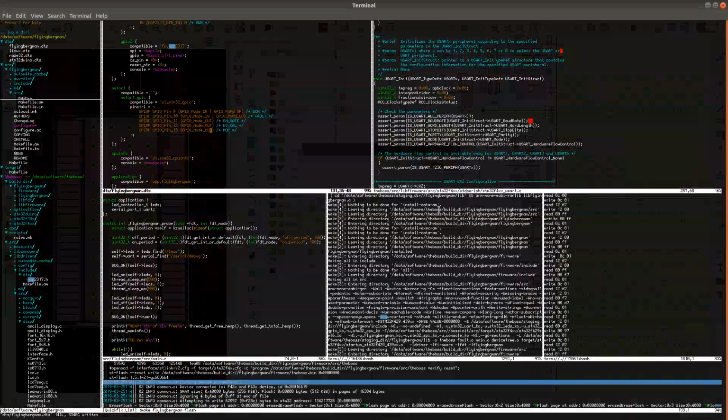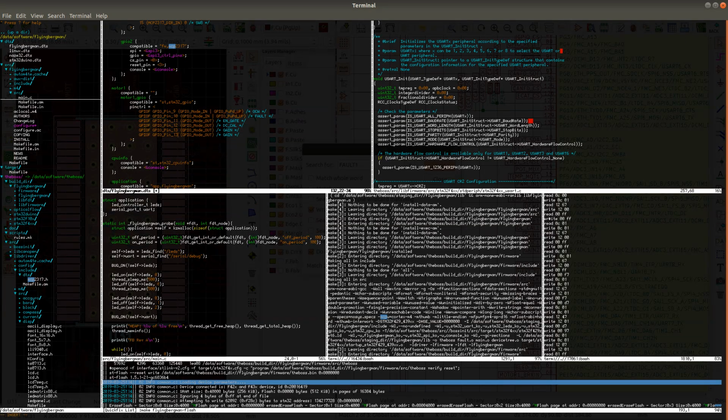Oh, I forgot the gain. That's actually the gain. Gain can be set to either 20 or 40 volts per volt on the current shunt amplifier input. So for every volt across the current sense resistor, we would get 20 or 40 volts on the output. Naturally, because the voltage on the current sense resistor is very small, the output voltage will just go up to the reference voltage, which is 3.3 volts in this case. So, gain and MOC.